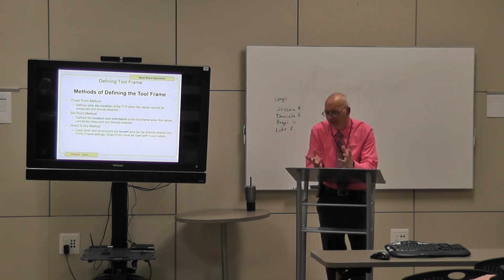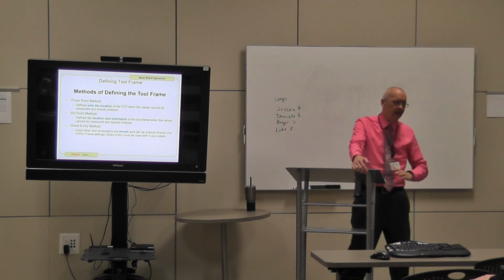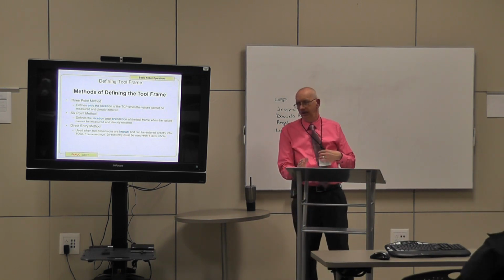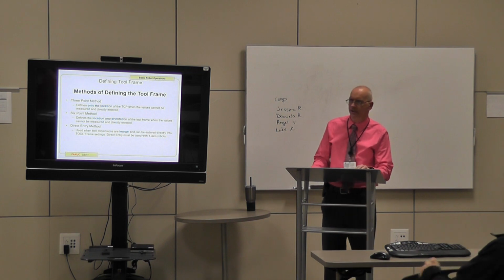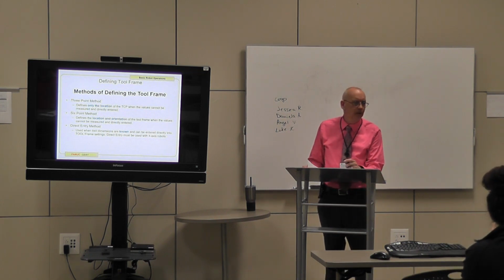Now, it's approximately 12 inches. It could be your company sprays out 5 inches to get a thicker coat. So whatever is at the end of that spray is what you determine is your TCP. Any questions over tool frame?